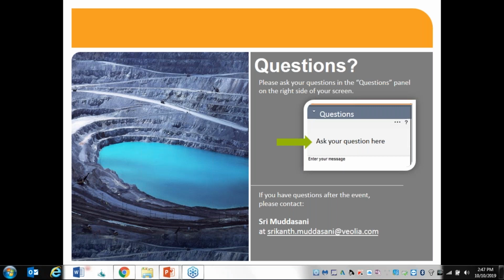But since this ettringite molecule has 31 moles of hydration, if you try to concentrate up, eventually if you don't remove it from your clarifier, it's going to get plugged up. So you have to have a continuous removal system, or you have to have a wasting system.